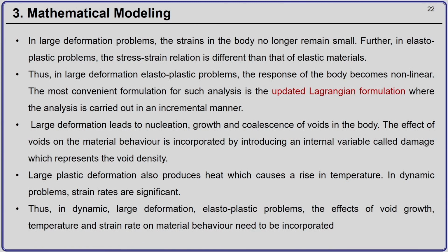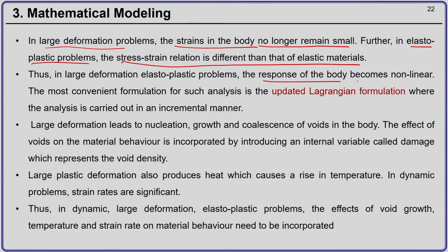So, in large deformation problems, the strains in the body no longer remain small. Also, in elastoplastic contact problems, the stress strain relation is different from that of the elastic material. So, the response of the body then becomes nonlinear, and to deal with such problems, the most convenient kind of formulation is the updated Lagrangian formulation, where the analysis is carried out in an incremental manner.